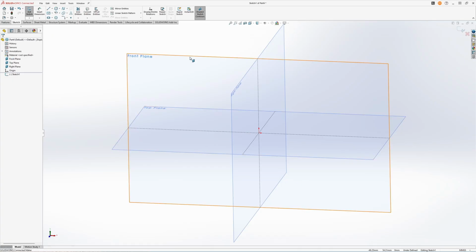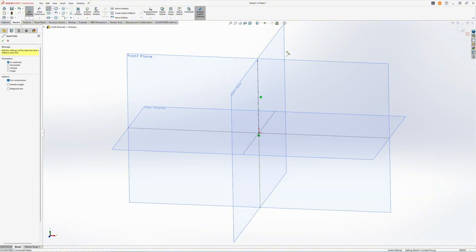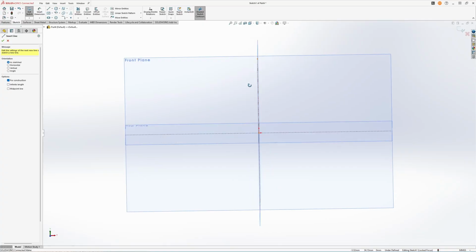So for that, I'll use a revolve, and we'll use the front plane because we want to do a revolve around this axis, the y-axis down here. So let me try to do that so you can see. So I'll do sketch and click front. I've already started a sketch now, and I'll draw a center line from our origin up and double click to stop. And so this just drew a line that we want to revolve our feature around.